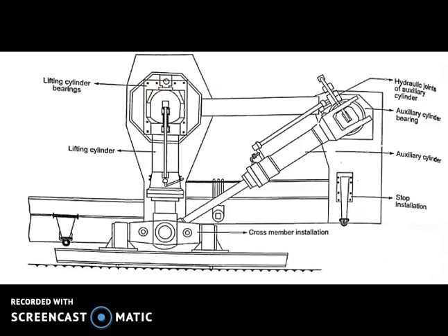In the eccentric type, there is a working shaft which is run through the gearbox by the working motor. Two eccentrics are mounted on the two extreme ends of the working shaft, one on the left and one on the right side. These eccentrics are connected by suitable linkage with the two shoes of the dragline.